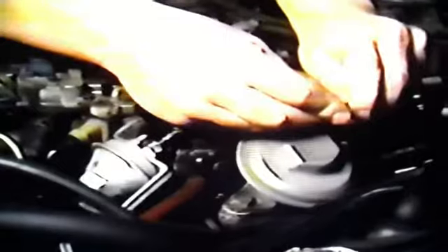Before beginning this new procedure, there are a couple of things you have to do first. For starters, you need to unhook the EGR and canister purge and unplug the PCV from the crankcase. Next, check to see the ECM is working properly. This involves making sure the computer is in the car with the correct prompt and that the connections are intact.